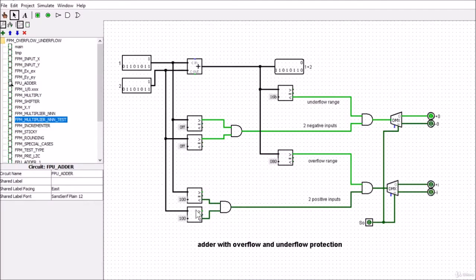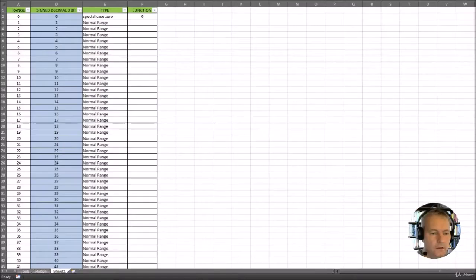You see that we've tested here for the positives to see if the value is less than this 100 in hex, and we've tested for the negatives to find out whether the values are greater than the value 0FF in order to get the negative values.